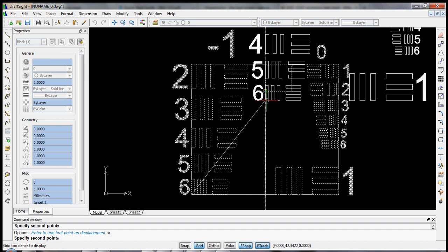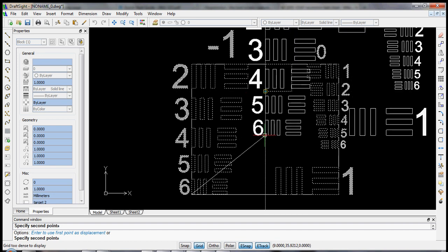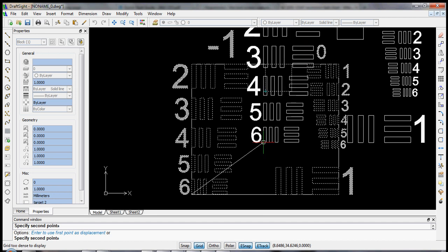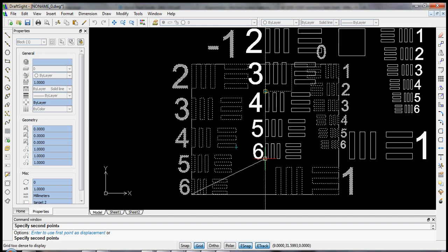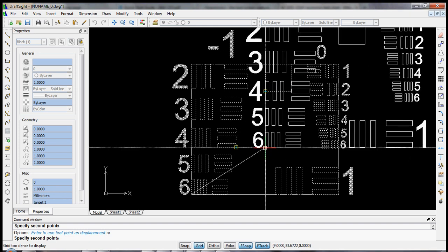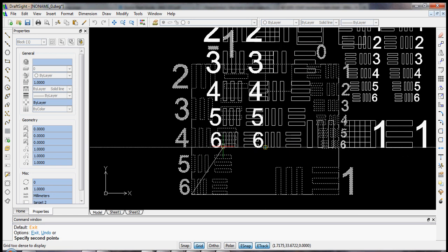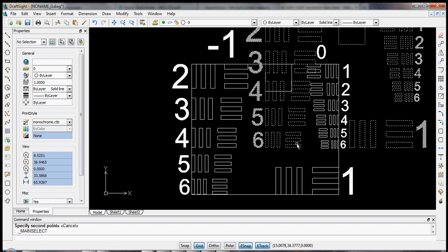And you see it's got a plus there. So now I have a construction line. And you see, when I get in line with it, I see a vertical line that I can snap to. Let's do the same on the 4th group. And now I've got 2 construction lines and I can click on their intersection. And I'm perfectly aligned with some of these elements. I'm going to hit escape since I only want to copy this once.